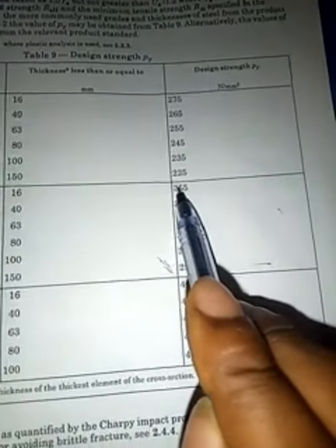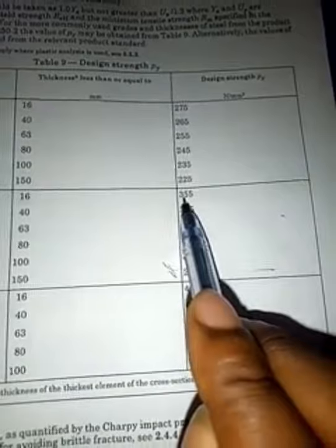All right. So after you get your slenderness ratio, remember our PY, we get our PY from table 9. This is what we should all be familiar with now. Your table 9 will give you your design strength. So where's our table 9 again? Go to table 9, look for your grid and your design strength. We had our S355 and our thickness, we assumed 100 by 75 by 10. So our thickness is 10, it's still less than 16. That means our design strength is still going to be 355. Remember that. So our design strength is 355 Newton per millimeter square.